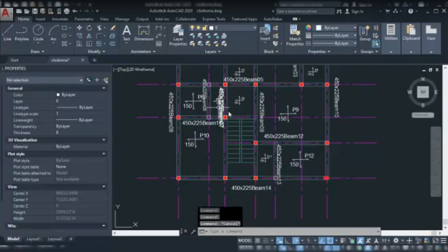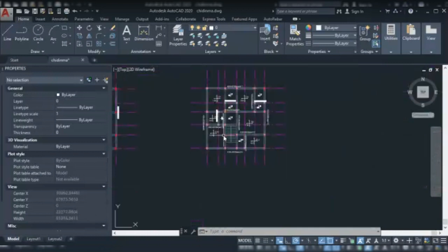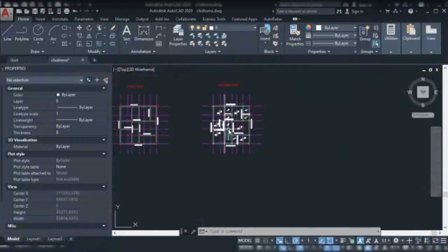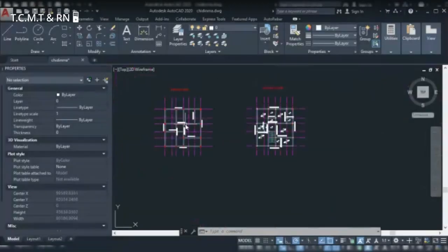So as you can see, this is where you represent a beam. Once we are given a general arrangement plan, and you see a dotted line, it means that the beam is actually carrying a slab. But this one will be left like this with a solid line because it's not actually carrying a slab.